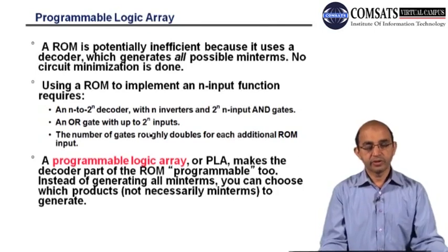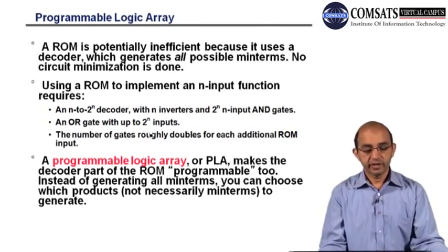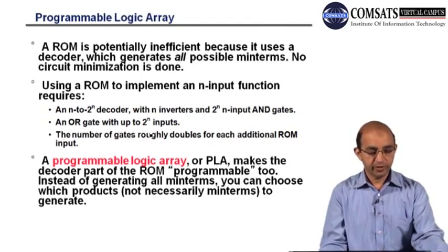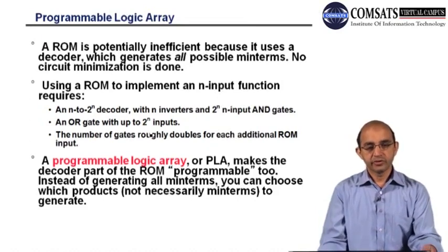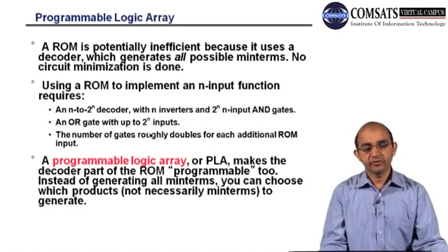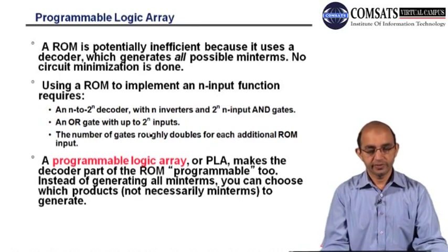And then we talked about the effective implementation of ROM. The problem with ROM is that we need the combinational circuitry and a decoder. The decoder is used in order to generate the min terms. If we have 3 bits for addressing, it will generate 8 different min terms. There can be certain scenarios where we are not using all those different min terms. So we need some sort of intelligence, or some sort of programming.